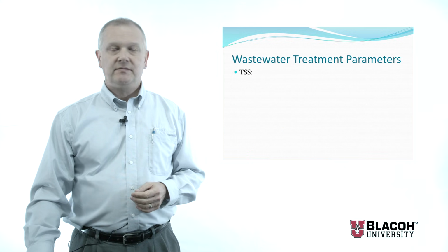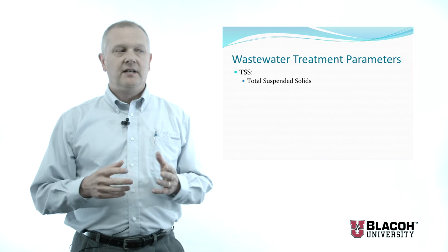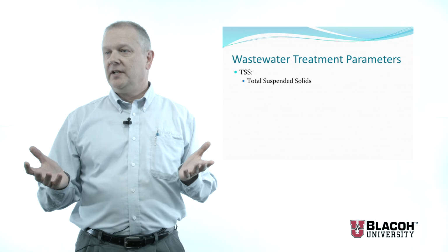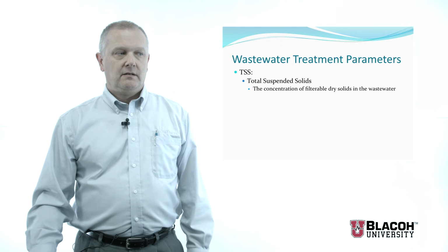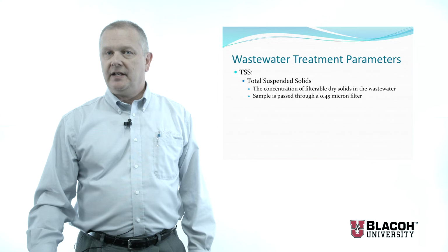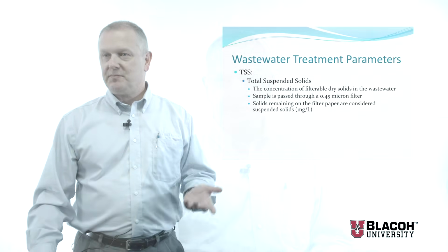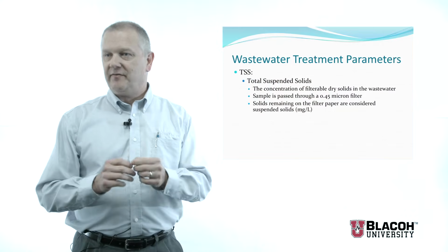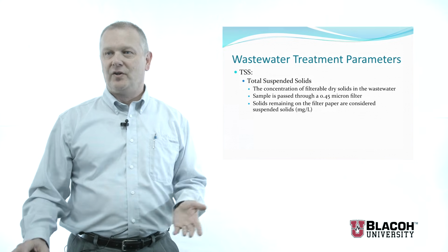Let's move on to TSS, or total suspended solids. This is a measure of the particulate matter in the wastewater. What we do is we run the wastewater sample through a 0.45 micron filter in a standard procedure, and whatever stays on the filter paper is considered suspended solids. Obviously there are some very, very fine solids that do go through, but we consider those dissolved because they're so small that essentially they are.